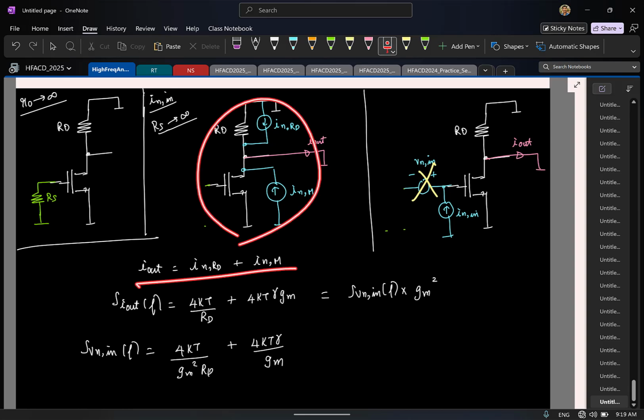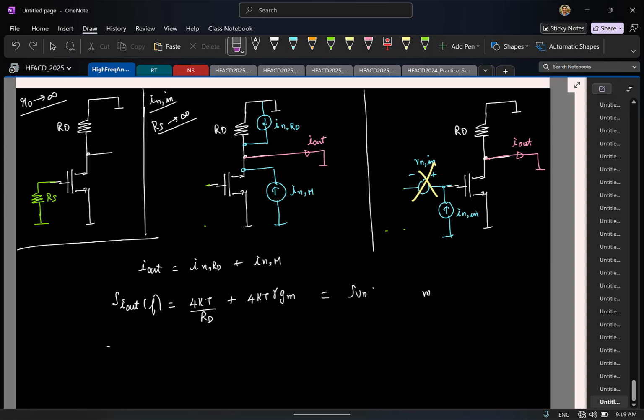The first step is the same. You might find some noise current. Okay, let's not go into that. Let's look at the transfer function here. So I'll erase this. Now I'm interested to find the transfer function from the noise current IN to Iout. What is that? If I apply a current source at the gate and I'm interested to find the short circuit current here, what will be the ratio of this to this? 0. Why? So will it be 0 or something else? He's saying the current cannot flow through the transistor.